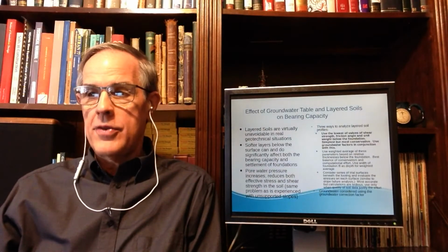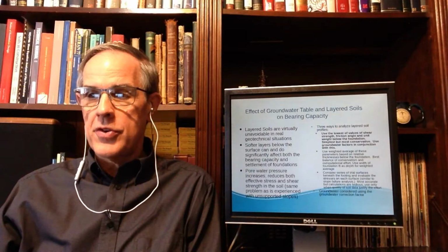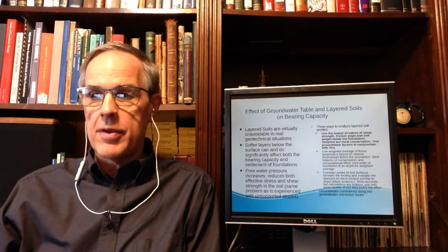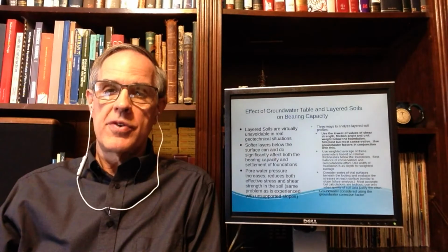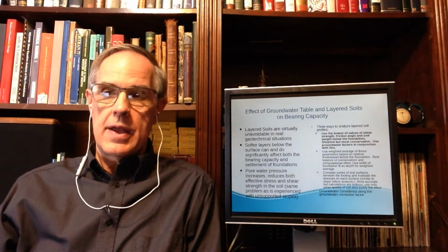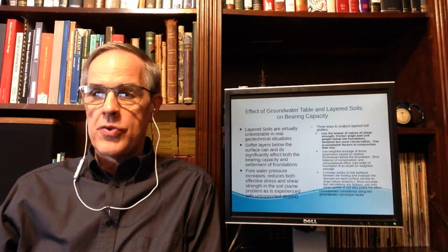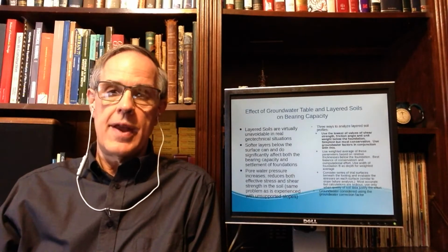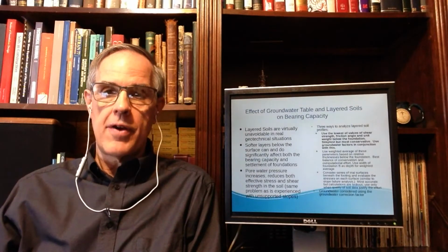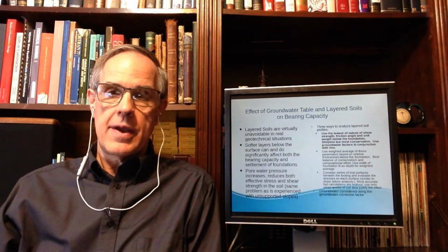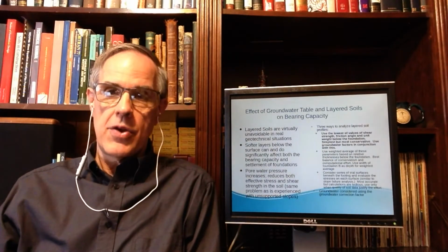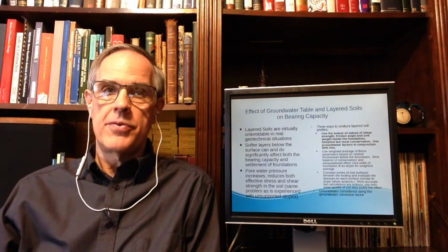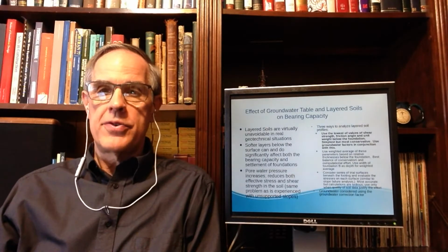Approach number one is to use the lowest values of shear strength, friction angle, and unit weight below the foundation. It is the simplest, but it is the most conservative. And use groundwater factors in conjunction with that. In other words, you use the groundwater factors I've taught you, you pick the lowest values for the layering below, and you go with it. That's the simplest way. That's the way we're going to start with.